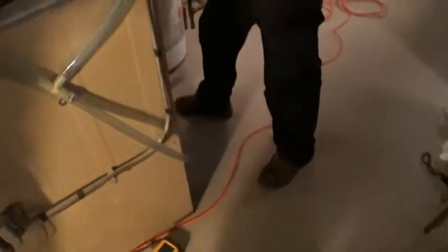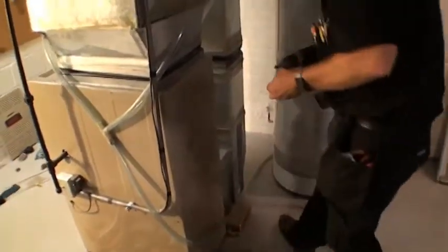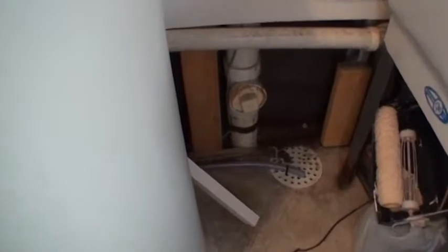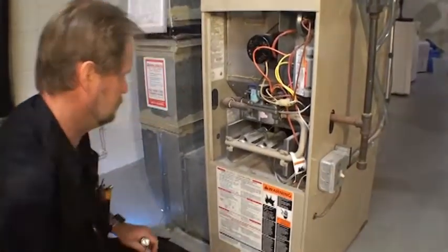Clean and vacuum all return grills, supply registers, and immediate duct openings. Check the condensate lines to ensure they are clean and secured to the drain. Install a condensate pump if the line runs across a walkway. Test the furnace emergency switch to ensure proper operation.